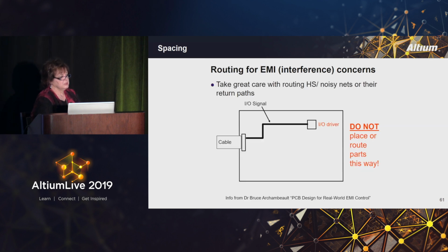Routing for EMI concerns. Number 1, you should never place parts this way. But I mentioned earlier how critical I/O is. This is a picture and information from Dr. Bruce Archambault. This is a wonderful book if you're interested in it. It's PCB Design for Real-World EMI Control. Wonderful, wonderful book. Very practical, good information for designing boards for EMI concern.